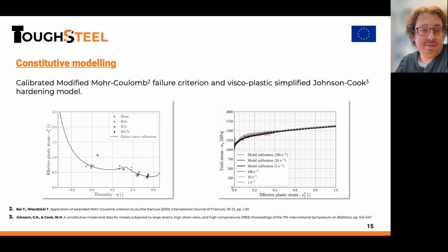And we can also see here that the local ductility, the one that the study mentioned, the one we're interested in when it comes to forming and crash, is dependent on the stress state. This is the shear one, this is uniaxial tensile testing, and this is basically the plane strain stress state. So we need to test for different triaxialities.